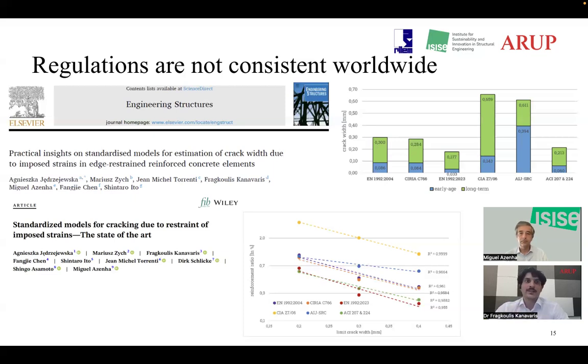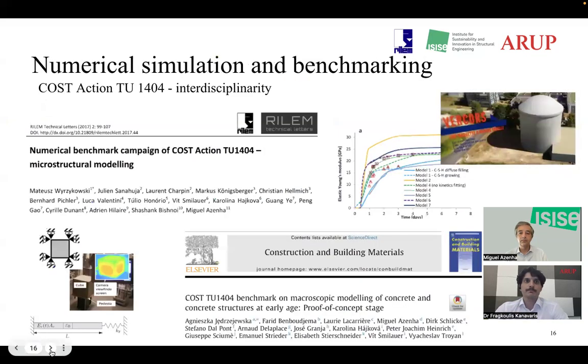It should be acknowledged that analytical approaches such as those in standards are must-haves, they're mandatory to facilitate design, but information on fundamental behavior can be obtained mainly from numerical simulation. As part of the COST Action TU1404, several numerical benchmarks were conducted, showing the importance of numerical simulation in controlling cracks, but also the variability of different modeling approaches when it comes to modeling hydration and shrinkage, and things can become quite complicated in that regard.